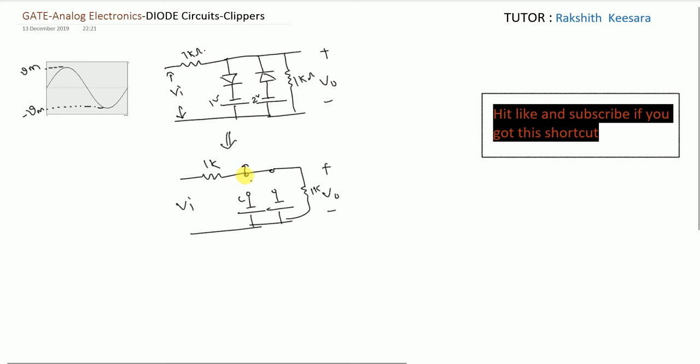Is it Vi? No, guys, here there are two resistors. So apply the voltage division rule. Here the voltage will be Vi by 2. This is the difference between the previous question and this question. So we should analyze everything with Vi by 2 now instead of Vi. So it is Vm, it is minus Vm. This is our Vi. But what we need is Vi by 2. So I am drawing Vi by 2 now. So this is the Vi by 2 waveform, guys.